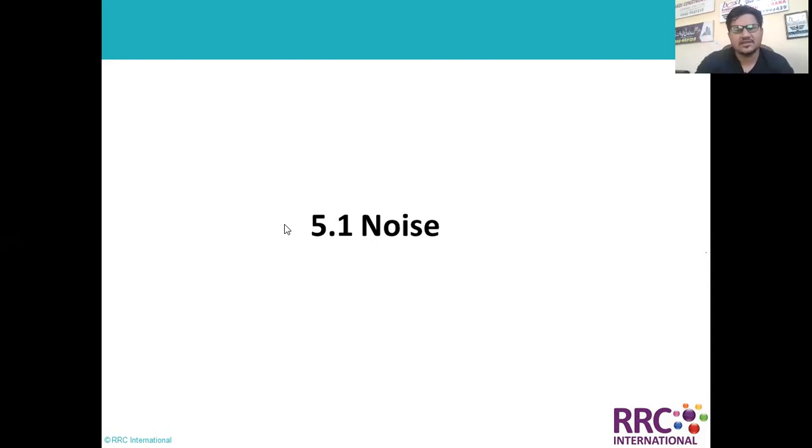For each rig, in the same standard format, he got the drawing or layout of the rig site, moved around, got all the readings, and then shared some average sound levels, area-wise or location-wise, and the most highly noisy areas where people could be damaging their health, or they can go deaf, with more probability of hearing damage. And then the company is responsible for putting in further controls on how to reduce it, like they might work more aggressively on their maintenance plans, or change some of the noisy parts. But the point is that he is not suggesting; the company itself has to find the best ways.